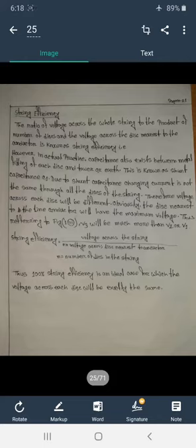String efficiency. The ratio of the voltage across the whole string to the product of the number of discs and the voltage across the disc nearest the conductor is known as string efficiency. However, in practice there is capacitance between the discs and tower or earth. This is known as shunt capacitance, and due to shunt capacitance the charging current is not the same through all the discs.